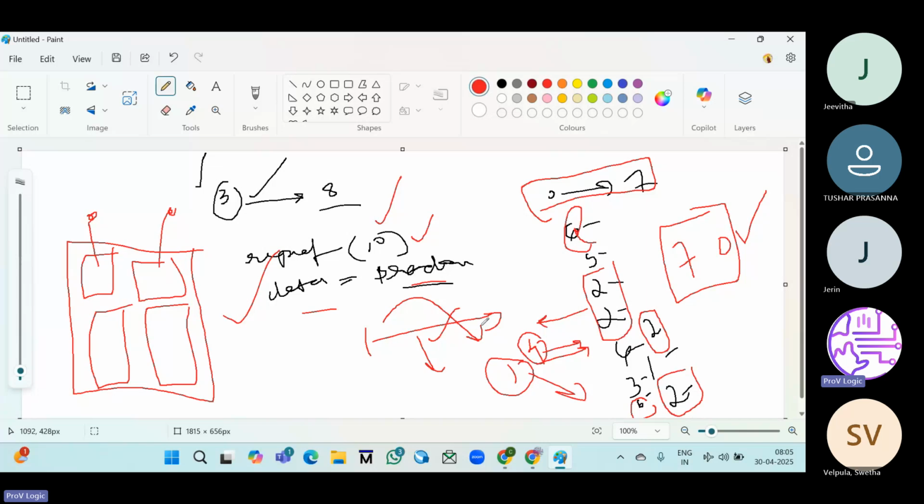Okay, so we don't resynthesize or we don't synthesize the RTL design. We don't even make changes to the RTL design. As a verification engineer, we make only test changes, because regularly we will get the updates from the RTL team, CDC team, and there will be different connected teams, right? If you go with post silicon verification, DFD, it will be connected with all the different teams internally. Regularly we will get some modifications for every week's regressions.